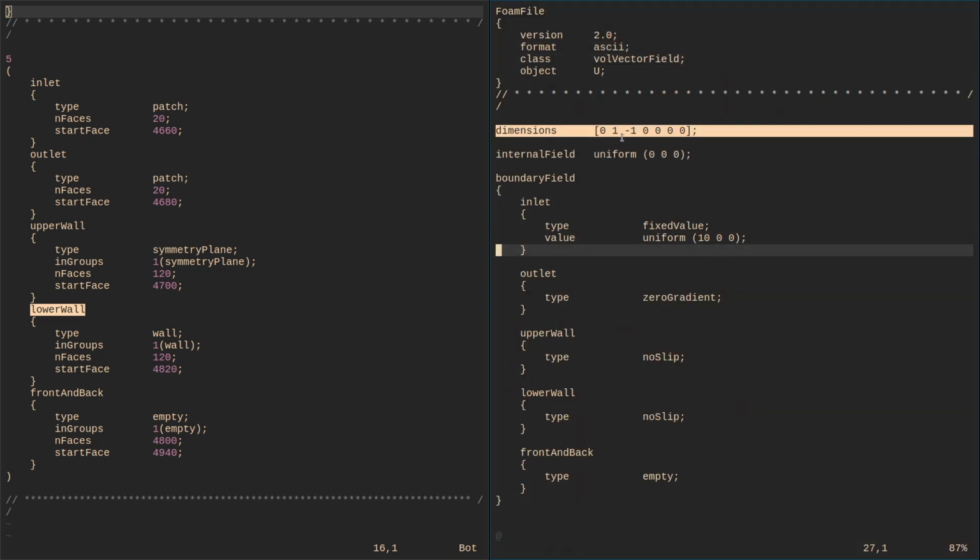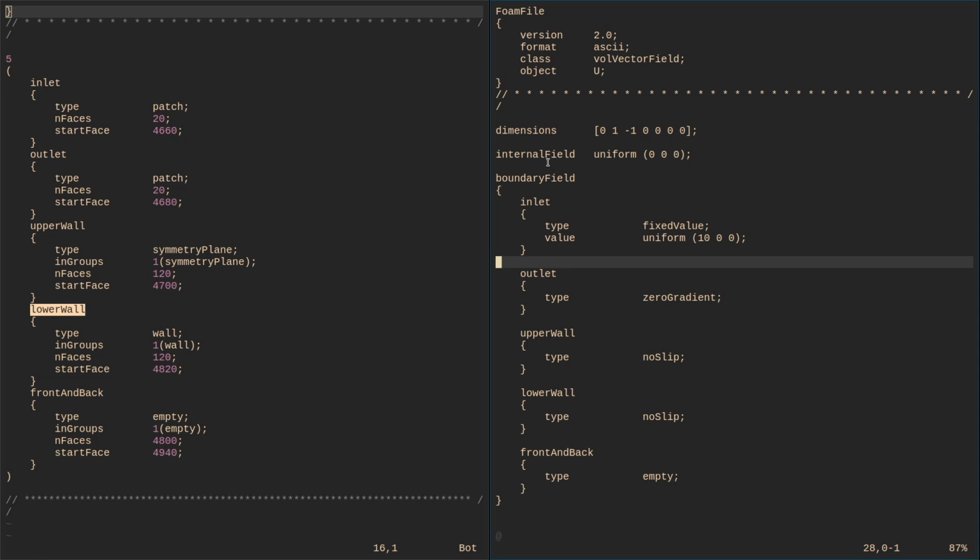So now we modify the velocity file. You do the same procedures. The initial condition is 0. The inlet boundary is a fixed flow velocity. Let's keep it 1 to avoid high Reynolds number, as our problem is laminar. You should calculate the Reynolds number before you run the analysis to make sure that the flow is within the range for laminar flow. Otherwise, the simulation will run, but the analysis itself will not be correct.